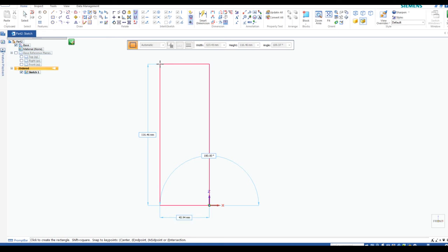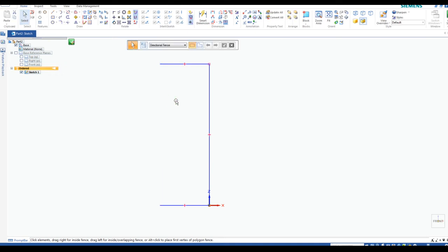Okay, I'm going to left click. There's my 2-point rectangle. I'm going to then select this edge and simply delete that, and then I get a backward C. The reason I need that is because if we take a look at the drawing, center to center of the bosses is 140 millimeters, and the spacing in between where the openings are is 70 millimeters. So we're going to use these lines as our location points for our bosses on both the top and the bottom, and we're going to use this line as our center line.